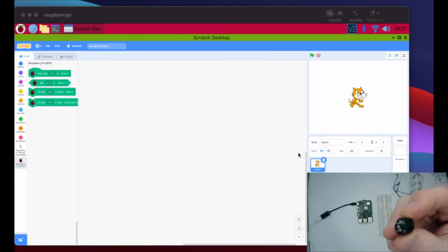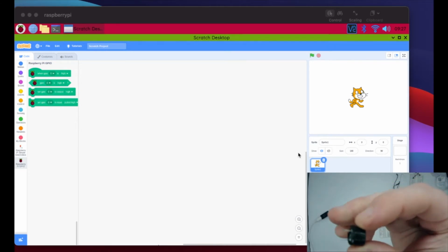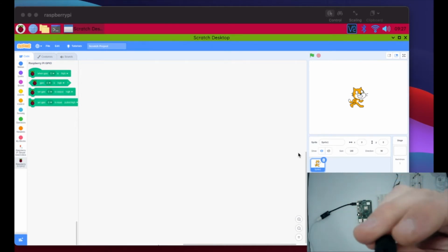Well, my legs are the same, so what am I going to do? It's probably really hard to see here, but on the top of mine, there's actually a plus sign to indicate that that's the positive leg. So oftentimes you'll see that happen, and LEDs will do the same thing. If the legs are the same, then there's usually a notch, which I'll show you in a future video so you can determine which leg is the positive.